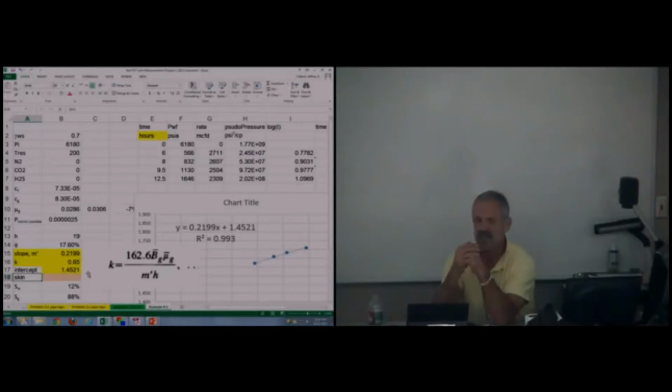And once we start getting into 6 and 9, it's a lot more fun. So are those corrections included in your functions? Because whenever we have contamination or a sour gas, then we're going to have a percentage of H2S. Let's just do a sour gas right now.